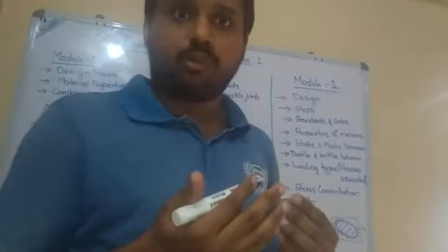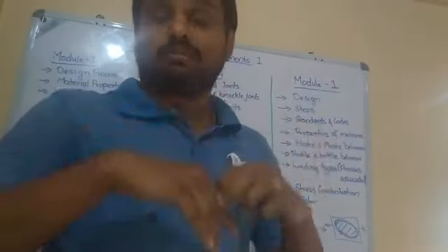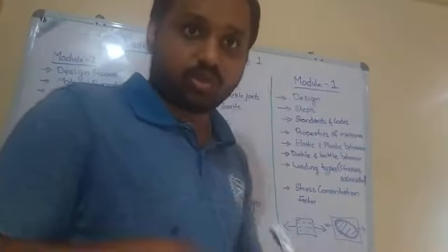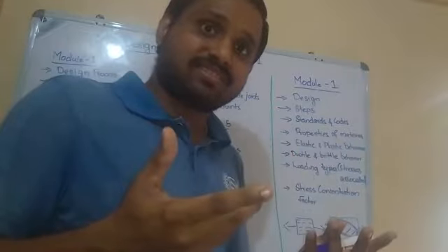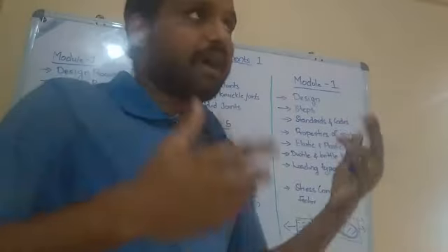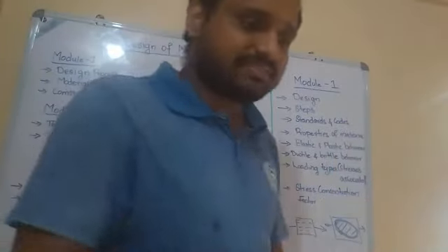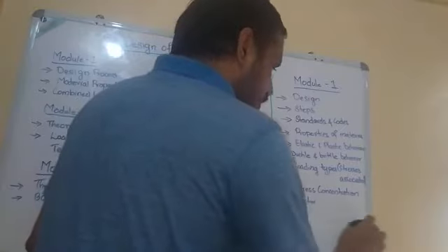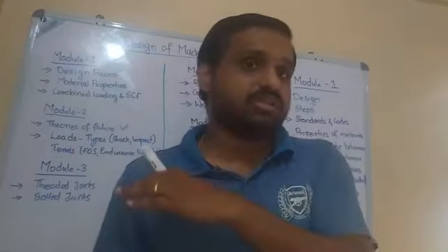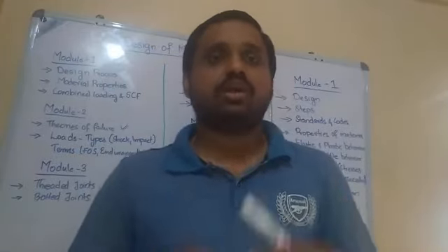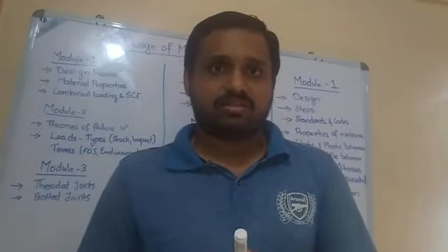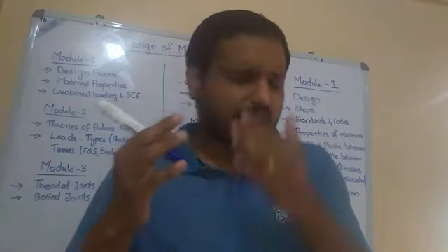So depending on the geometry, the stress concentration, the maximum stress that happens on this object will be increased. If the maximum stress is increased, you need to design accordingly, or it cannot avail much load, right? So in all this design purpose, you have to find out the maximum stress, in which area or which part, and what the maximum stresses are.